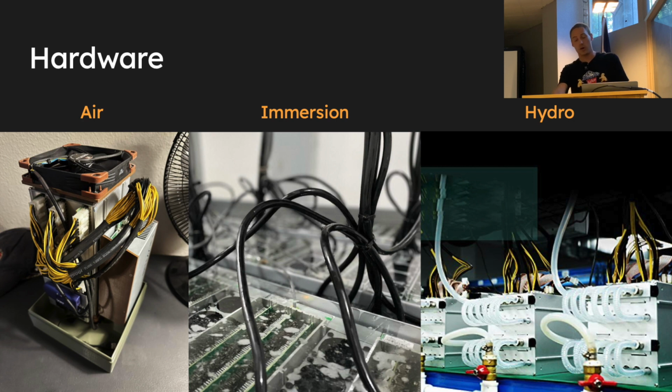And then you see hydro here on the right, which is much more specialized. It's a much higher-performing way of cooling just the areas you need to cool. So in this case, instead of all these fins and heat sinks that just add more surface area so you can reject that heat to convection, you have what's called a water block, and it's literally on top of all of the ASIC chips, and it has all these jets, and it's literally jetting fluid onto the chips. And this way you can use water, which is conductive if you don't demineralize it, but you get high convection coefficients because of the jetting, so just high velocity, you're throwing it at it.